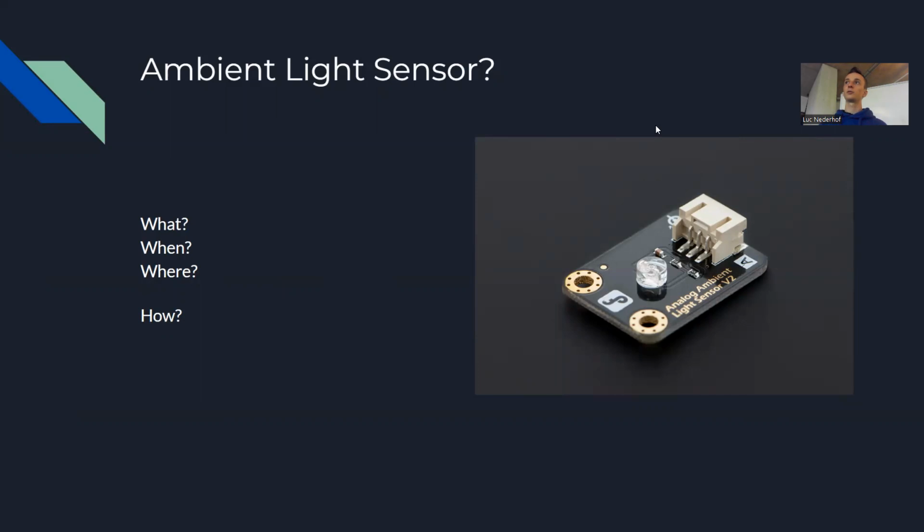So if you've got a really bright light shining on it, that might make the resistor more resistance, you might get less voltage, and you might get a pin to trigger a low state, or you might get it to trigger a high state. So you would definitely use them in scenarios where light is very, very important. Maybe you're using it for a sensor that makes lights turn on automatically at night. You know how street lights will turn on automatically. I think they actually sync with the sundown times, but you could make a lamp that turns on when it gets dark and things like that.